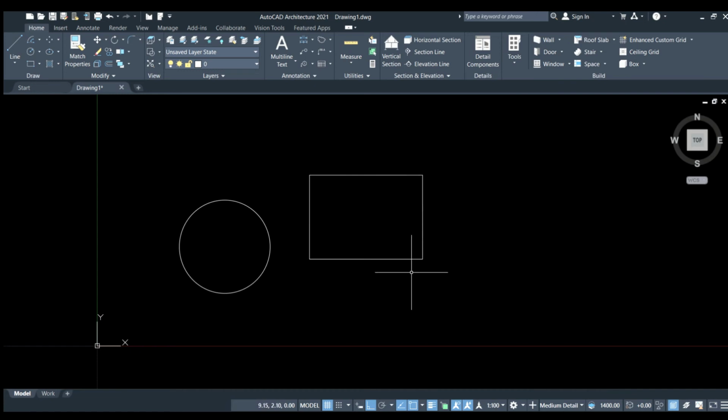We drew this rectangle at random. We don't know the dimensions of this rectangle. But when the object snap is on, it will tell you the midpoint, the edges and the center. Similarly, at the circle, what is the known point? It's the quadrant, so it will be indicated in a green kite. And when you go to the center, it will be a green circle.